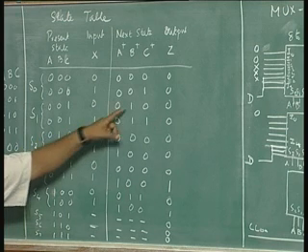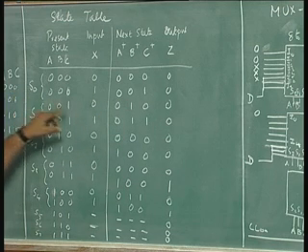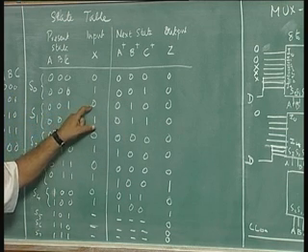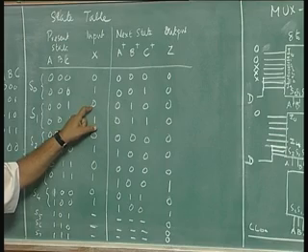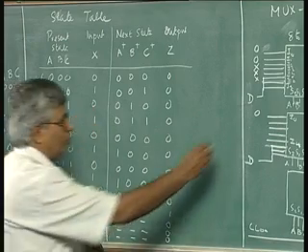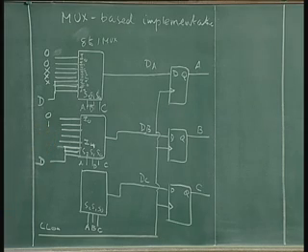Next state of the flip flop B is 1 from the present state S1, whether X is present or not. So, that is a 1. So, what should be the next one? 0. The circuit is in S2, irrespective of the value of X, next state of flip flop B is 0. S3, same.